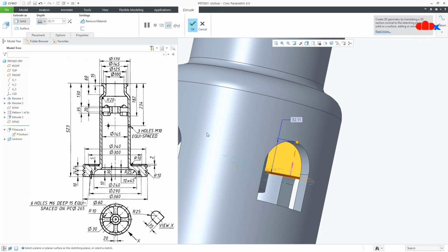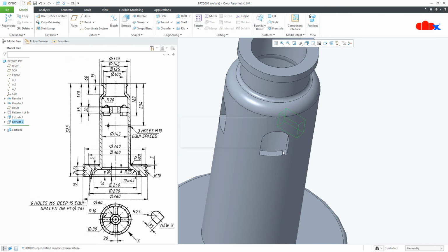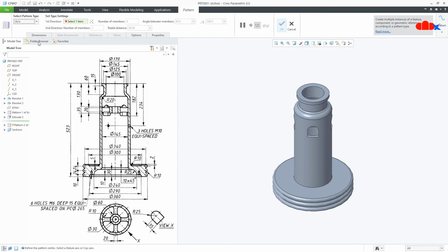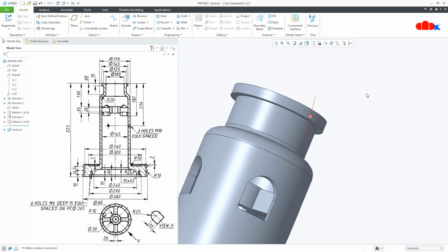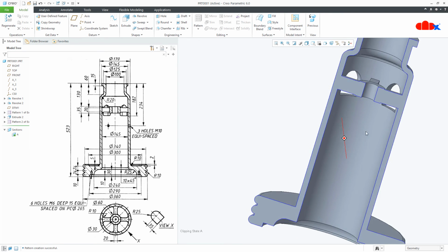Now this time material should be symmetry since we have created a mid plane. Now once again pattern it, same axis pattern. Select the same axis, 4 items, 360 degree. Say OK. Now if you go to section view, you get your section like this.